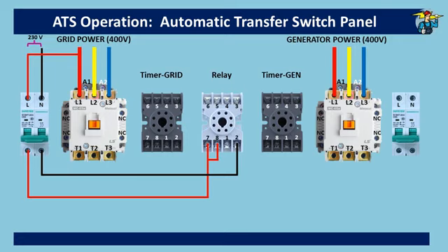Now, relay output from number 6 is connected to the grid timer power supply at number 7. Neutral supply also connected to number 2 of grid timer. This will make sure, as soon as relay is powered, normally open points of 8 and 6 will close, and grid timer 2 gets power simultaneously.